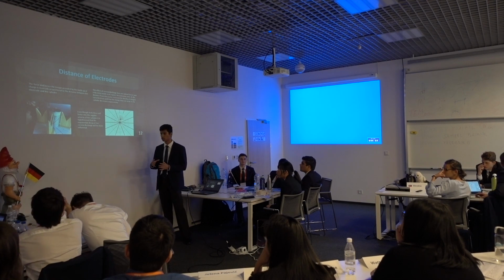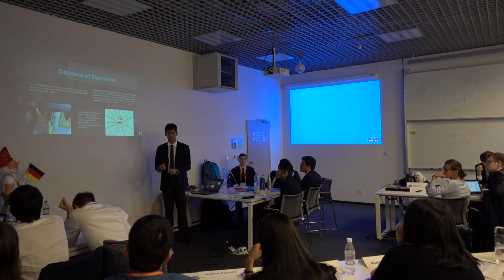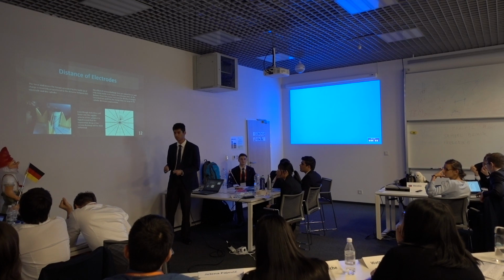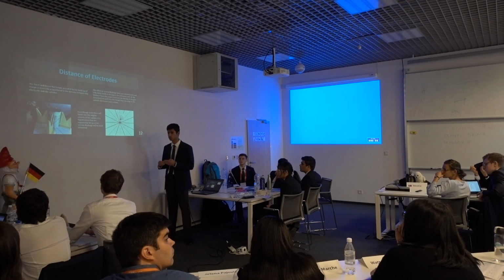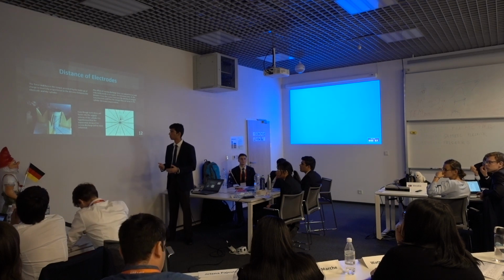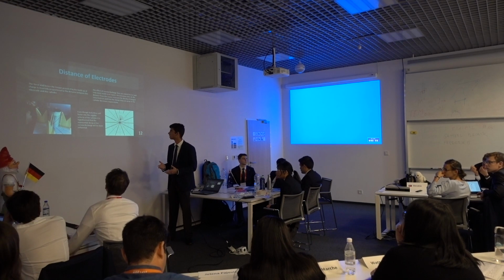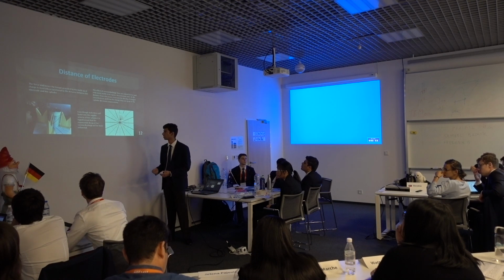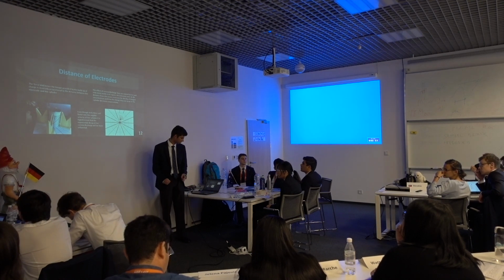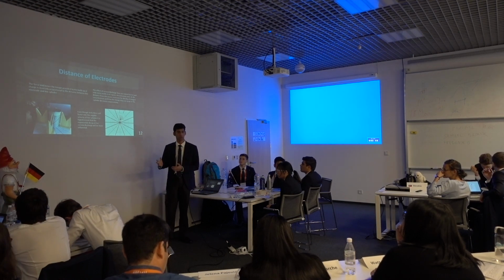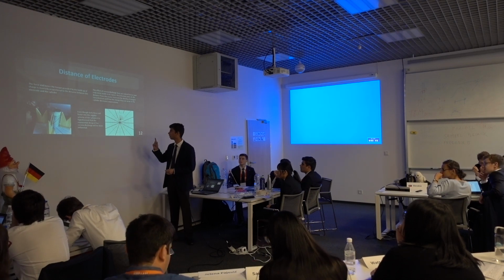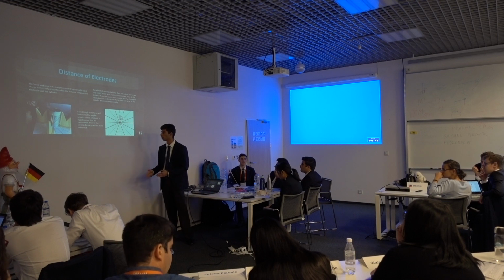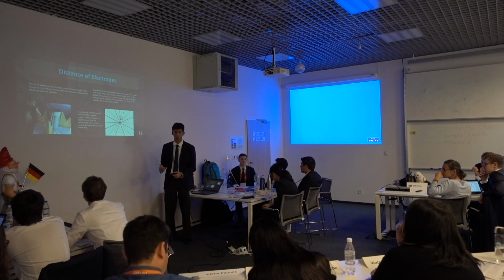This is the zone after which the electric field is not strong enough to actually ionize the air molecules. And as the distance from the source increases, the density of charged ions or electrons, and thus the charge they can spray on the actual cylinder, decreases exponentially. And even though there are two effects at play here, it was hypothesized that the exponential decay of the charged particles due to corona discharge will be more influential.